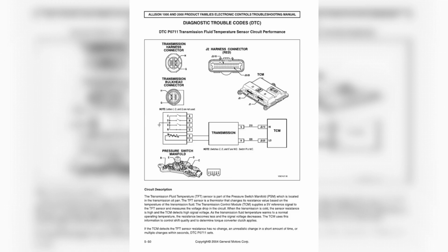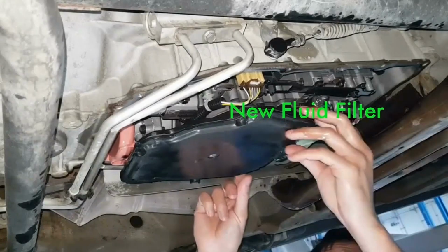2. Transmission behavior changes. Unusual automatic transmission behavior may accompany code P0711. This may manifest itself as abrupt gear changes, delays in shifting, or even an inability to engage certain gears. 3. Gear shift difficulties. Problems with the transmission temperature sensor can lead to gear shifting difficulties. Gear changes may become rough, jerky, or occur at unexpected times, affecting normal driving.